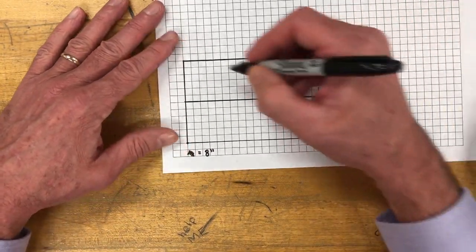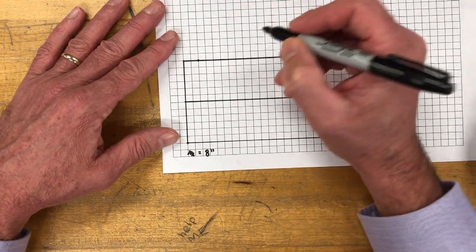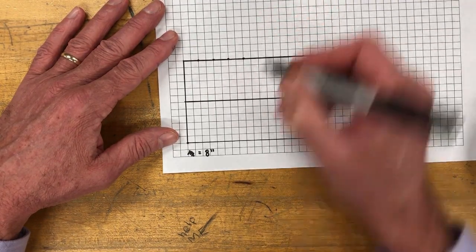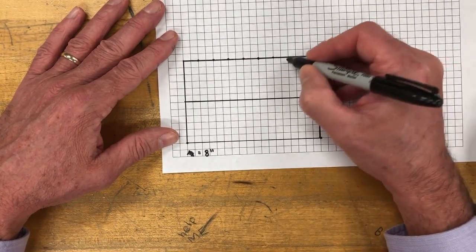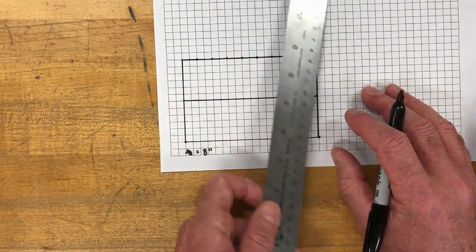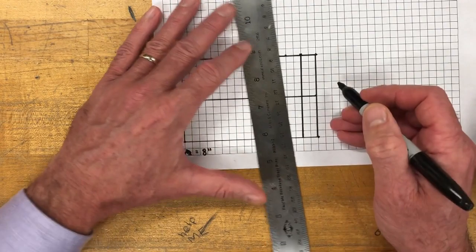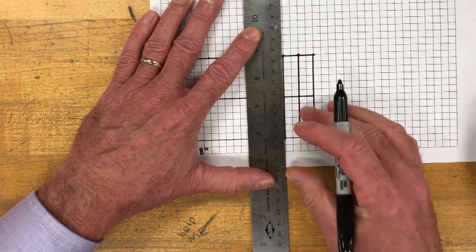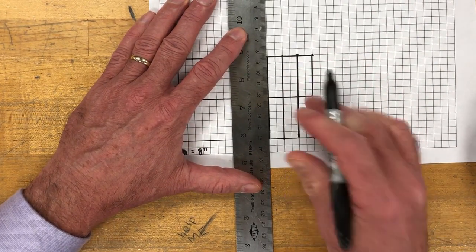Now, the other thing we're going to do is set up where our trusses and our wall studs are going to go. I'm putting a mark every other block, because that's 16 scaled inches apart, and that's how far apart our trusses and wall studs need to be set as well. So with that information, I'm going to sketch in some vertical lines. The upper parts would be the trusses, the lower parts would be the wall studs.